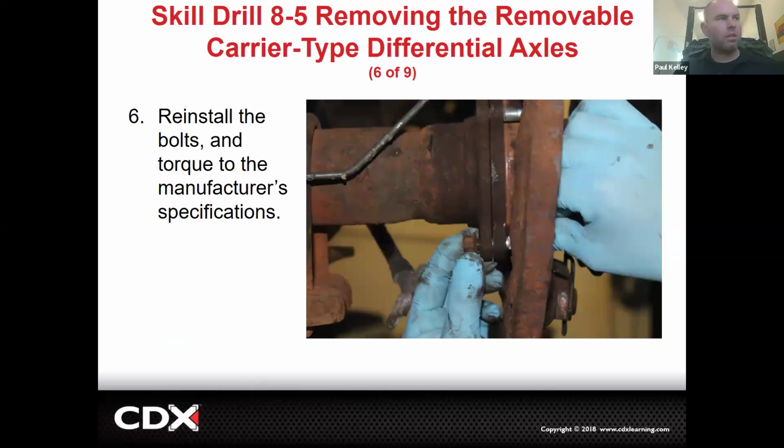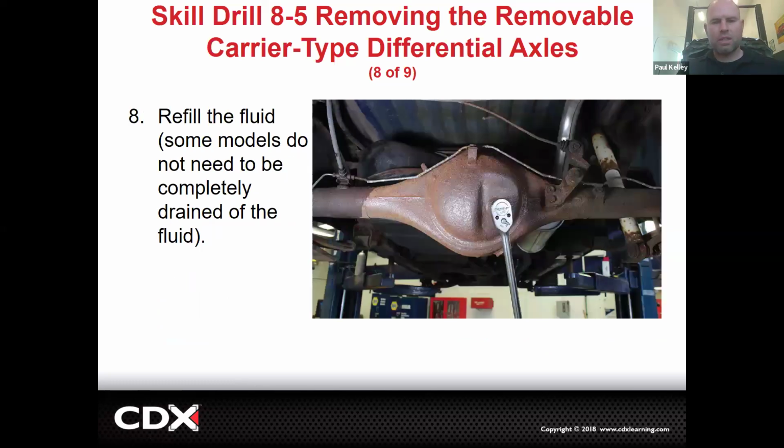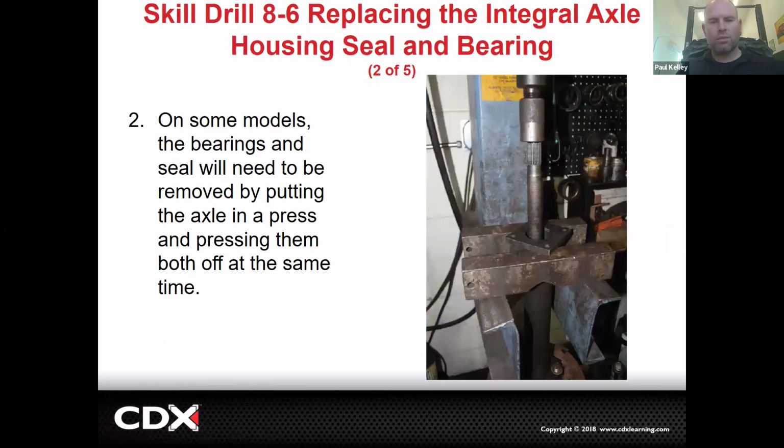We're reinstalling the axle. And then right here, we're bolting that bearing plate back up on this 3/4 float style. It's kind of floating, but not totally. All right, then putting all the brakes back together. Checking the fluid. Now, this is a cut from a different one.